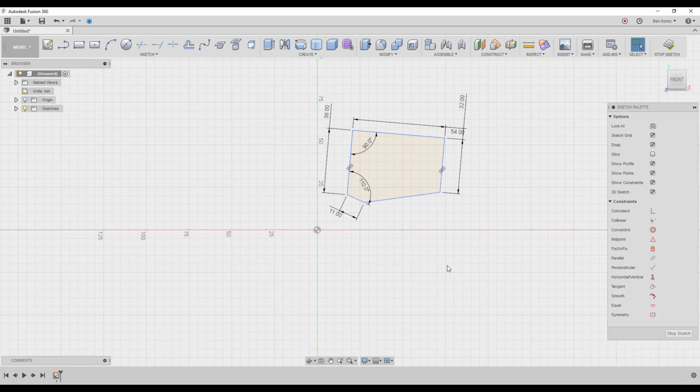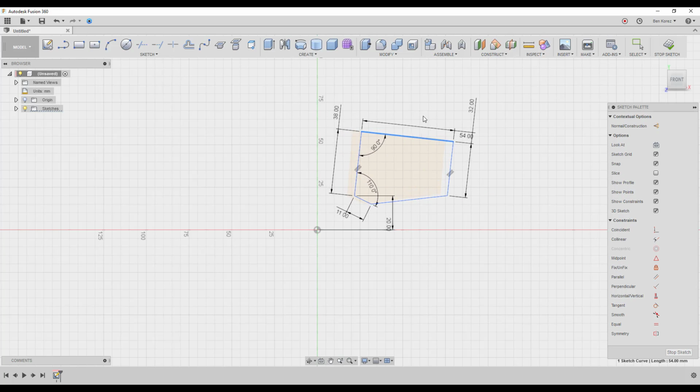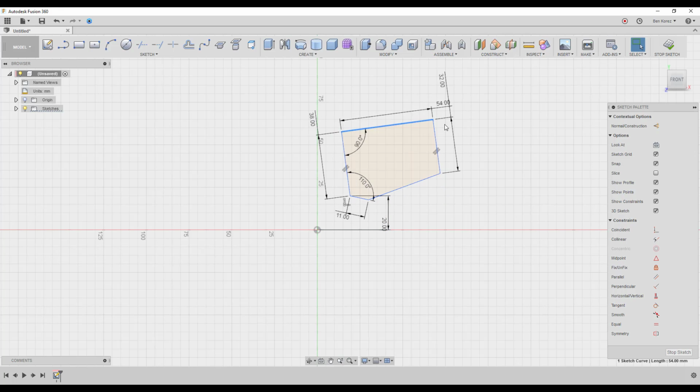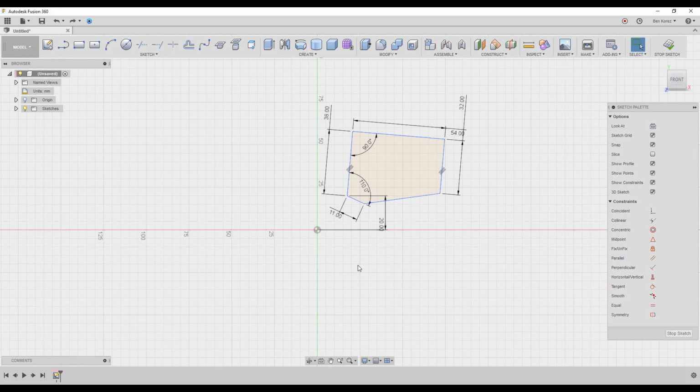So in order to make it black, I'll just say it like this, fully constrained, then again we have to continue constraining it. For example, we can say that this point to this point, we can give it some kind of a distance, okay? Let's give it something like 20 millimeters. Still nothing, because if I try, I can still move it around this axis here. So I need to continue constraining it so it's not going to move, which means I need to fix another point.